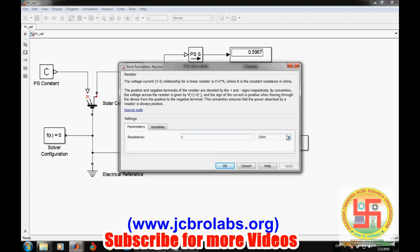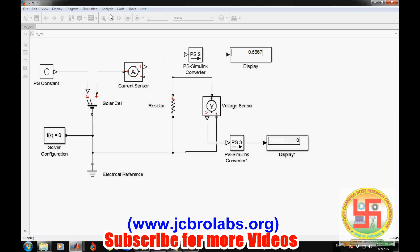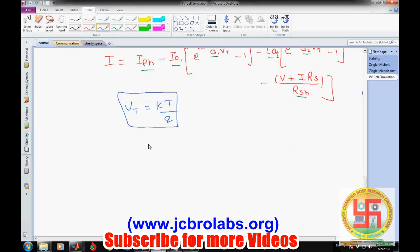Now we increase the value of resistance to 1 kilo ohm, so it is like an open circuit voltage because resistance is quite high, so voltage 0.6 and current has been reduced to 0.6 milliampere. Okay, so this is how we can simulate a solar cell in Simulink.